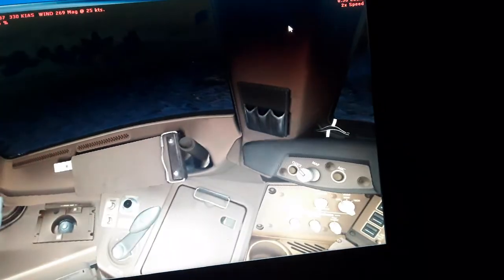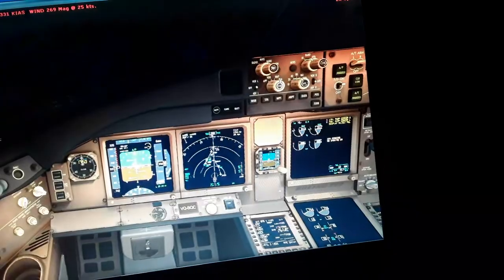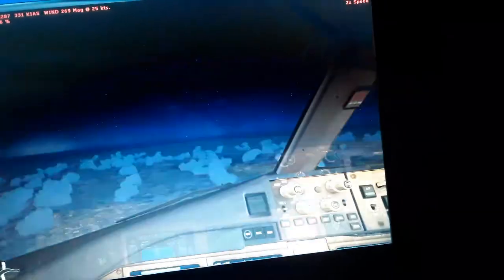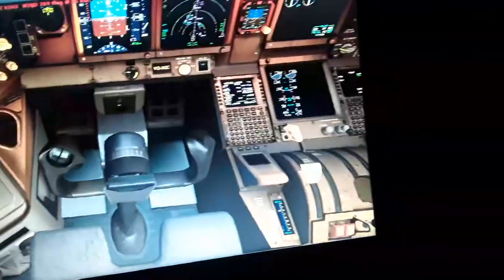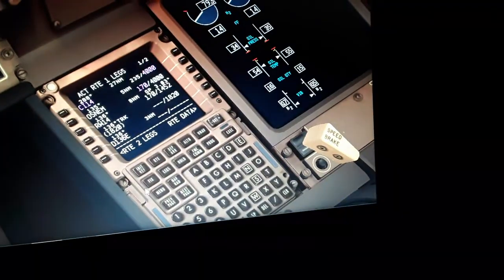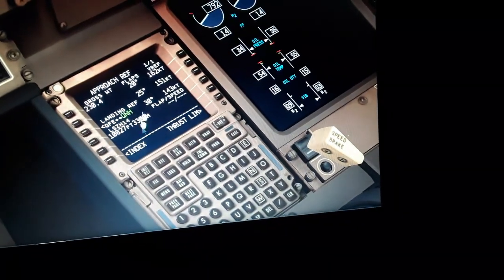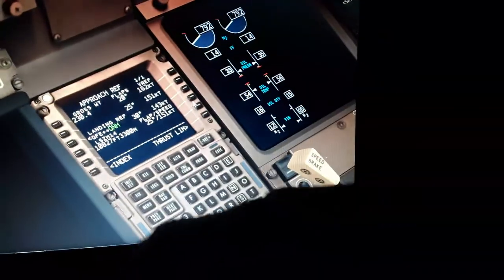We have a few more minutes left to go actually. So we need to make a very fast approach and landing. Use a simulation acceleration mode here. And also select here initial reference flaps, 35 degrees flaps and slots.